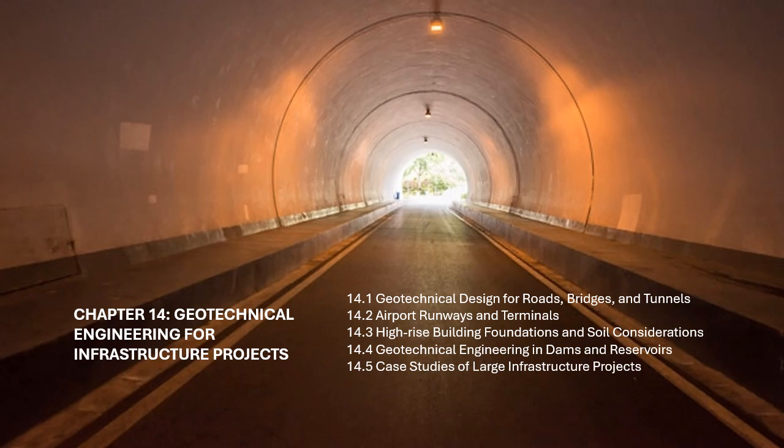Geotechnical innovations. The design and construction incorporated advanced techniques such as ground freezing to temporarily stabilize soft ground and prevent groundwater inflow during tunneling operations.